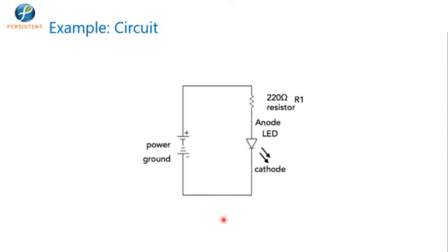The connections were something like this, wherein we added a resistor in series to the LED. The cathode, which was the smaller leg of the LED, was connected to negative and the other end of the resistor was connected to positive, and we completed the entire electronic circuit. And after connecting it to your Arduino board properly, with the Arduino board powered up from the supply drawn from the laptop, the Arduino board working voltage is 5 volt, as we already discussed.